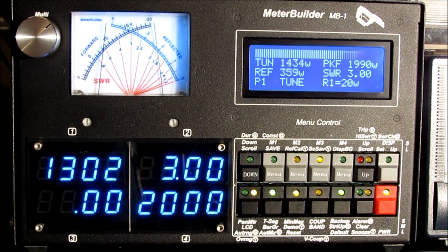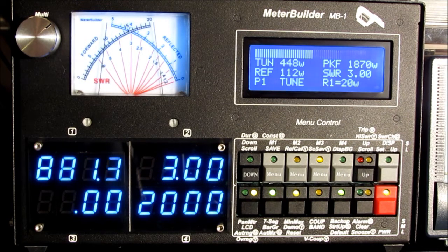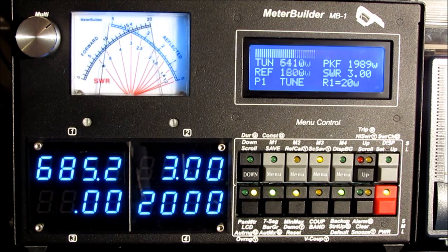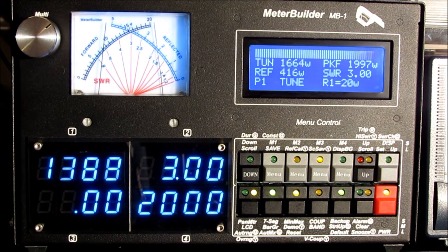Rather than just maxing out at the full-scale value for that particular range, soft overrange allows you to define during the calibration of that panel meter how much excursion above the full-scale value you want the meter to go when an overrange is encountered. So you can tell by looking at this that you have an overrange. You don't know exactly what the measurement is, but you do indeed know that you have an overrange.